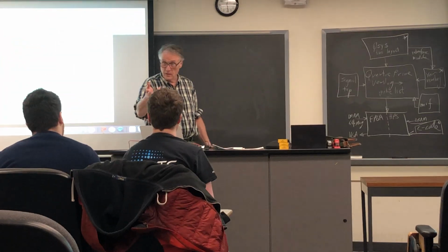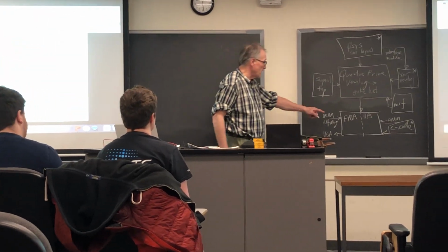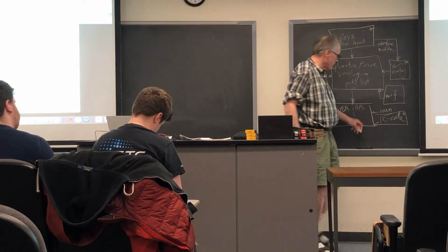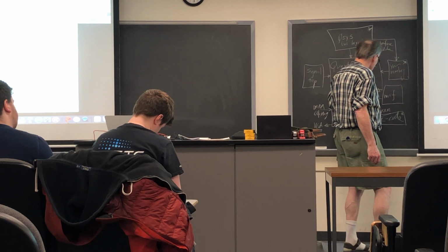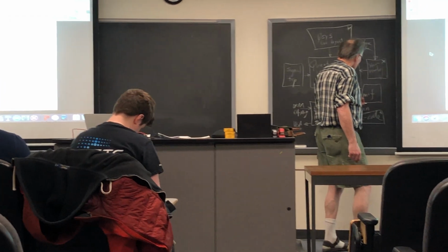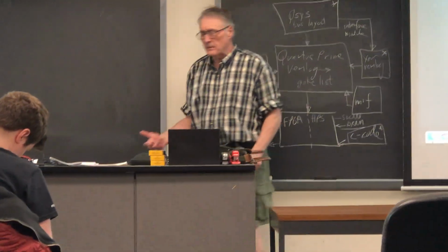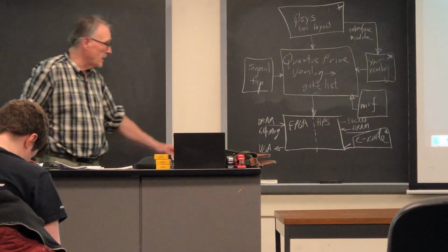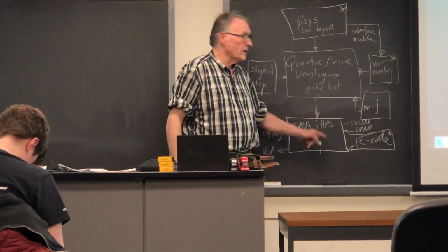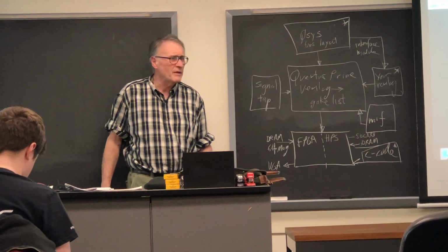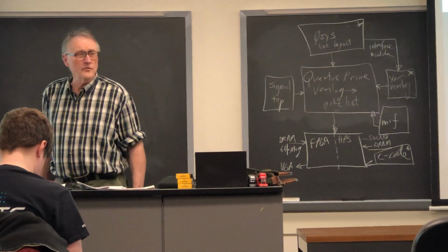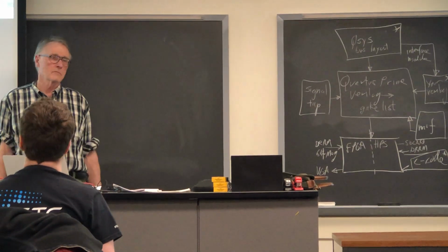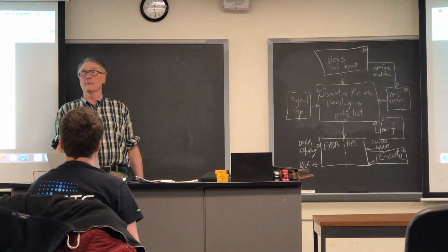Yes. Well, where does Linux fit in all of this? Linux runs on the HPS. I haven't drawn it, but there's an SD card here. And there's a boot process. Linux boots up off an internal ROM. It bootloads the Linux image off of the SD card and starts to execute. It boots in maybe 10 seconds. That's a full Linux distribution. Has all the usual stuff. You want to edit in Emacs? Have at it.